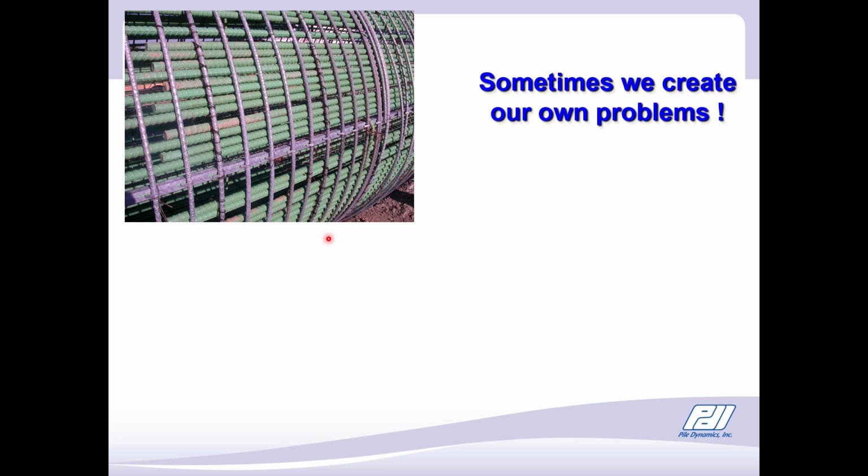Just as a side note, sometimes we create our own problems when we're drilling shafts. In this particular case, we have overlapping bars over a section of the shaft. And if the bars are that close, we're going to have a hard time getting the concrete that's pumped inside the cage to flow outside the cage. And we likely could have an issue in the concrete cover, the concrete outside of the cage.